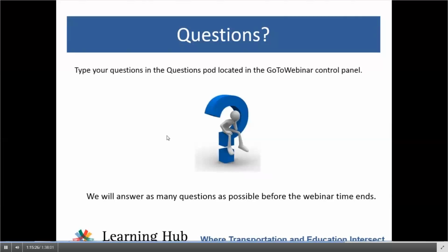Let me jump in here, Bastian, on that one. It is arbitrary. We on the committee had a lot of discussion about it in developing the method, and the thinking was at an interchange, some drivers will pass through both intersections, some through only one, and so it was arbitrary. Well, let's just take the scale for a signalized intersection and multiply it by 1.5.